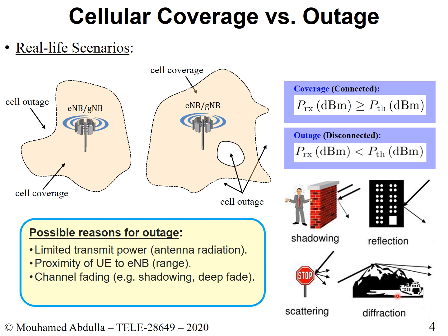You also have the phenomenon of diffraction. Diffraction generally happens when your electromagnetic wave, or your signal, hits a sharp edge. In this example, you see a mountain. In a city you don't have mountains, but you have buildings, and these buildings could have sharp edges around them. If your signal hits a sharp edge, again, the signal will get offset in a different direction.